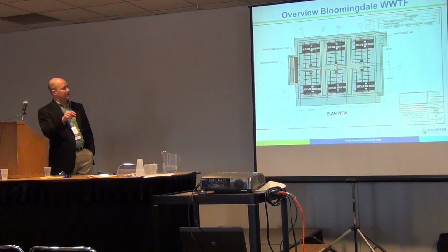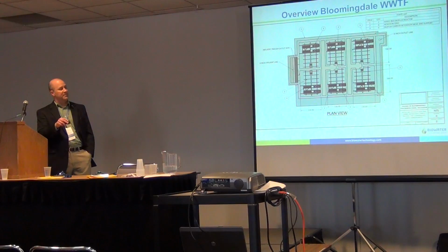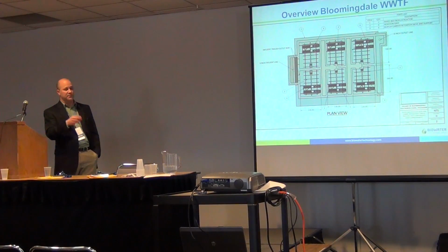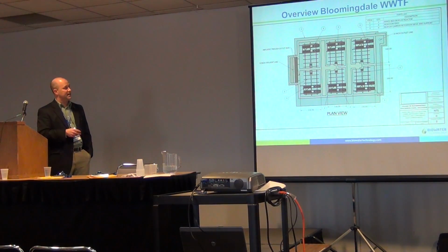So an aerial view looking down, you can see the aeration grid. You're getting full floor coverage of the basin, so the media is moving around very nicely. And you see the retention sieves here that allow water and sloughed off biomass to exit the basin from one to the other and continue down through the train while holding the media back in the tank.